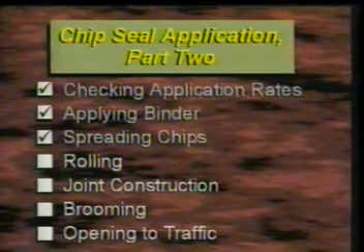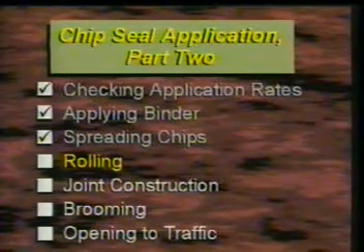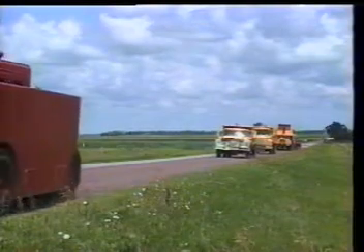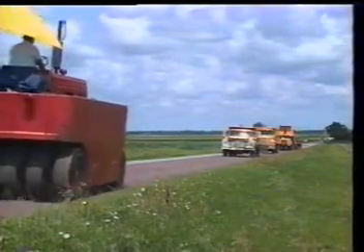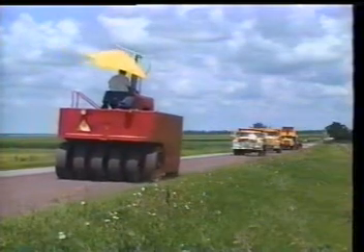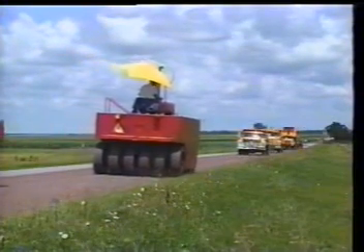Then it's time to look at the rolling. Rollers follow closely behind the spreader to make sure that all chips are firmly seated in the oil and that the chips are lying flat, not one on top of another.